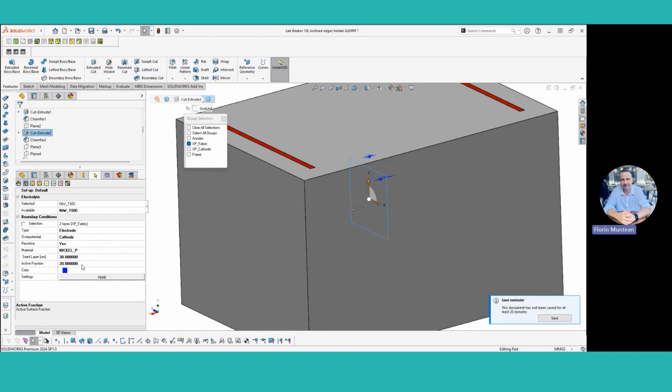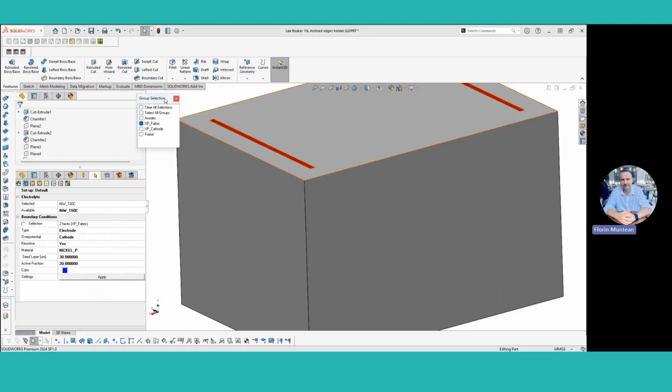So instead of using 1, so the surface is just what we see, we said this is 20 times bigger. And this will account for the 3D structure of the carbon fiber. We established this value performing a few iterations, and based on our findings, we decided that 20 is the most appropriate value for this case.